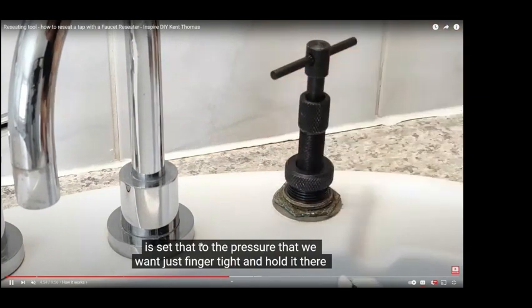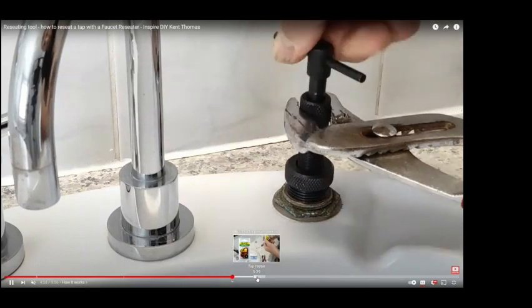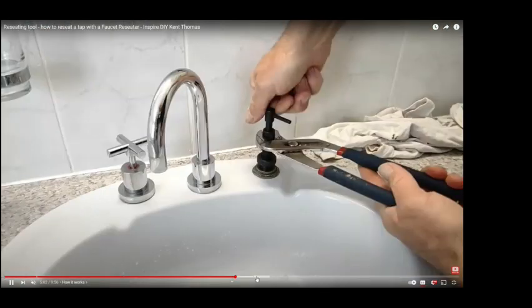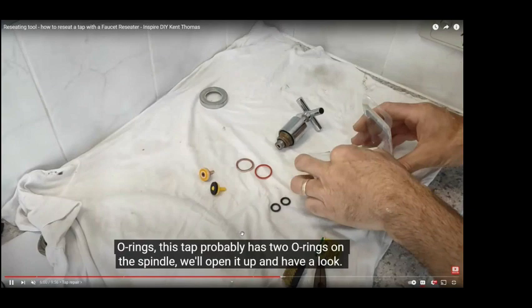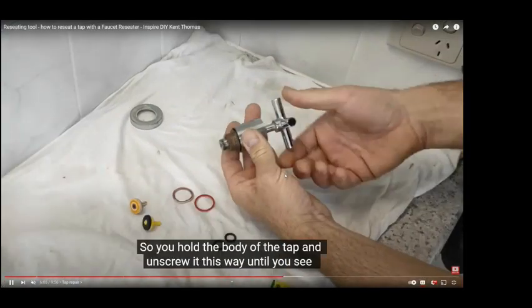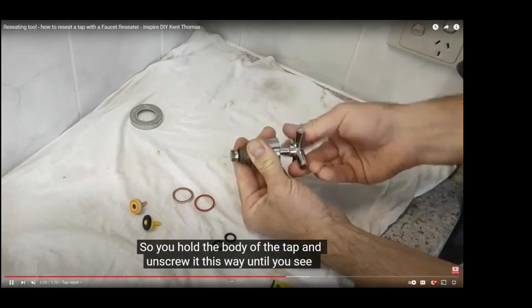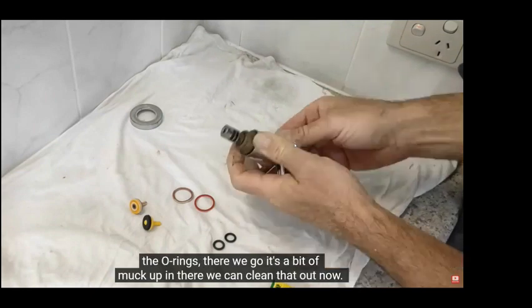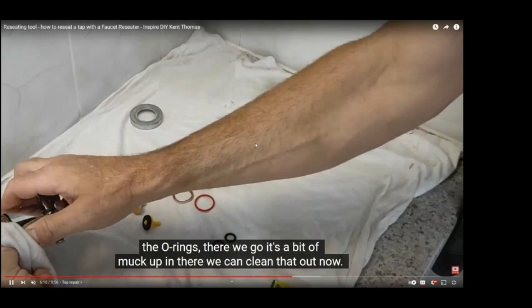So there he's talking about how he's overdone it. Now he's going to hold that. If you can't hold it with your hands, there's something wrong. You shouldn't have to hold it with multigrips. Speed it up a bit. He hasn't even taken this part off because that handle should come off. So it looks like he doesn't know how to take the handle off. This one's got 2 O-rings, which is a bit unusual. Normally they only have 1.